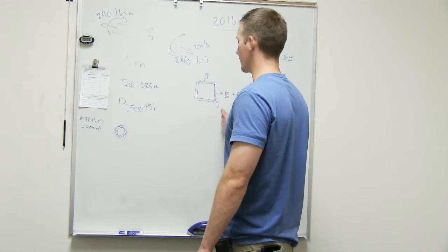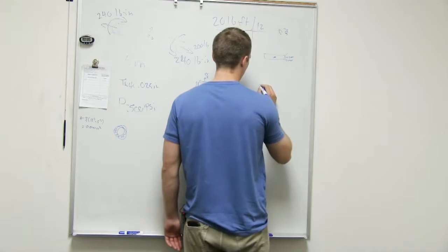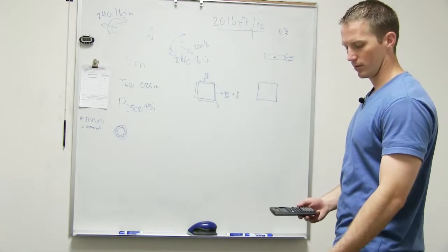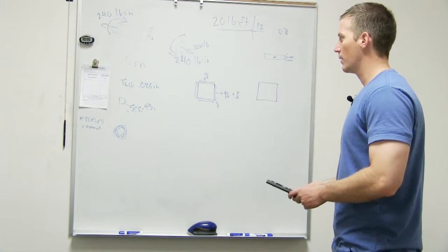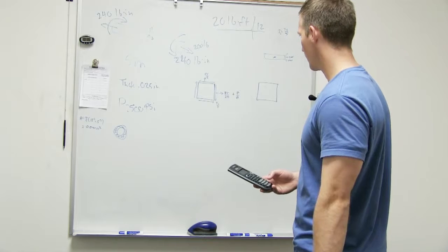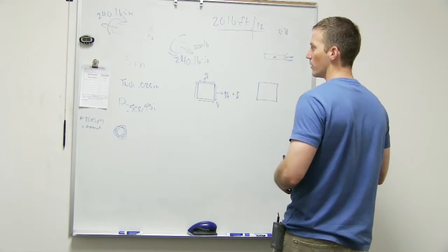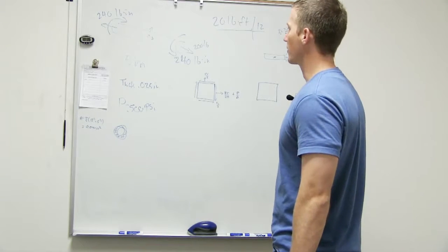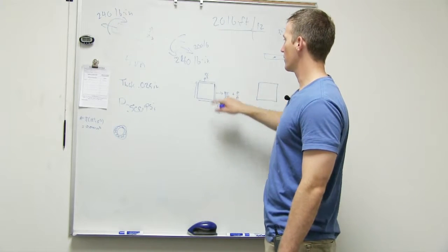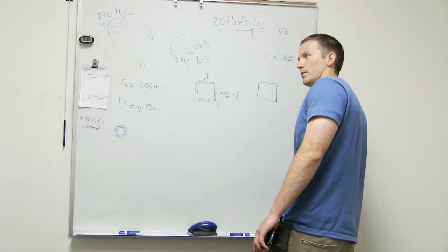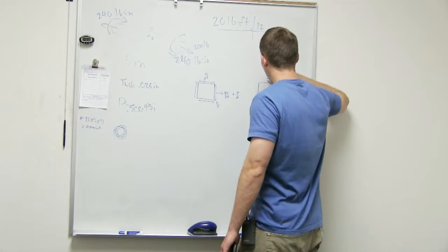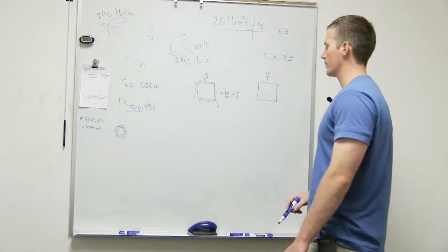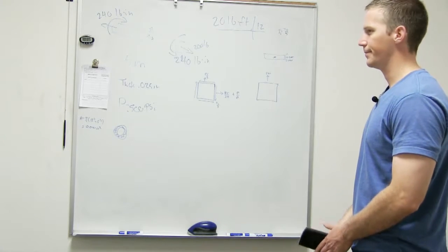Well, we already have everything then. We've got to calculate our values. So let's calculate them. Which one do you want to do first? We'll start with PR over T. We're using the 500 for that one, right? Yeah. 500 times our radius. Are we using the 0.55 minus 0.5? The inner radius is what you use. It doesn't matter about the other one, because these equations are set up for inner radius. That's why they only give us the inner radius. We don't actually use it unless we're trying to calculate area. So PR, and then the thickness is 0.025. Times 0.5 divided by 0.025.